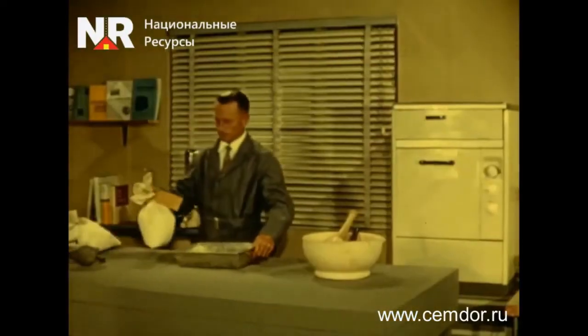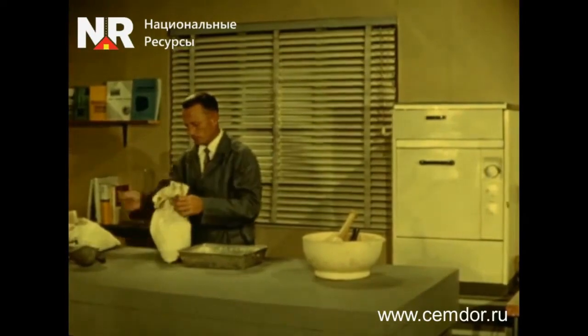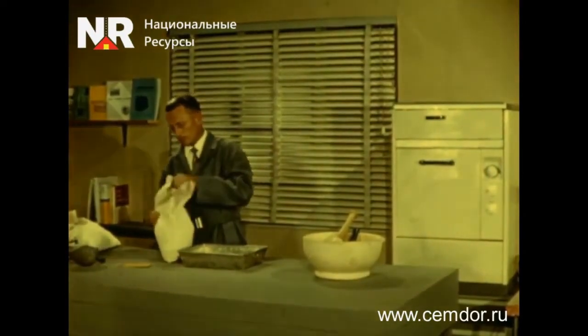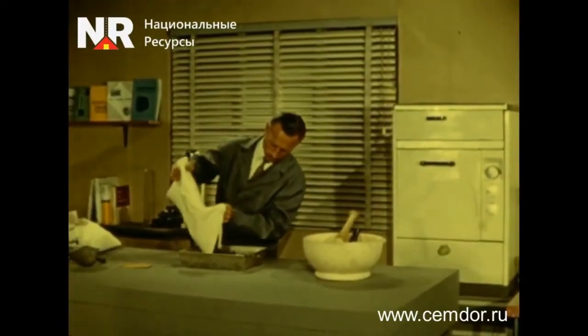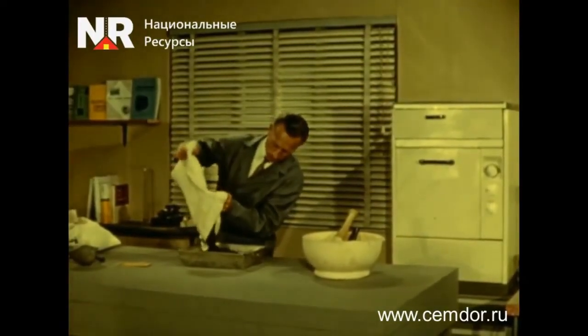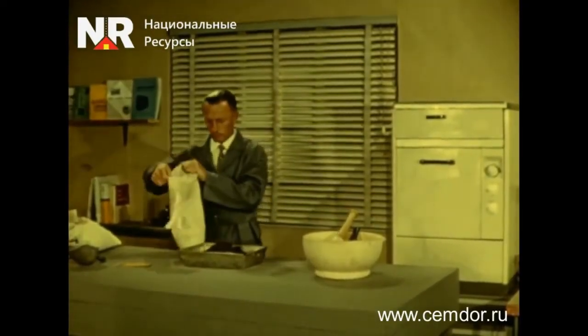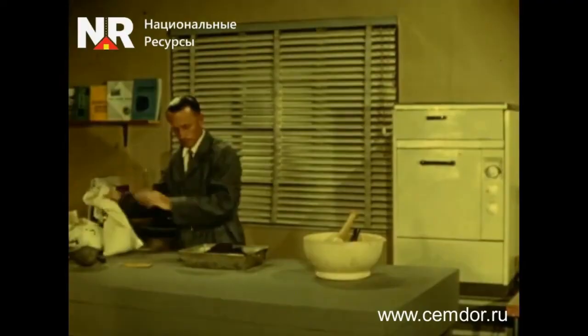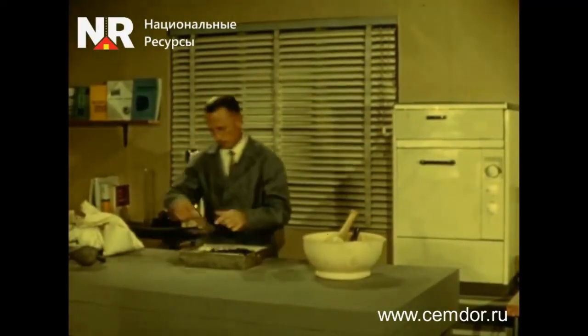In the laboratory, the samples undergo several tests to select the soil concrete mix, determining the optimal amount of cement and water to obtain soil concrete with the required set of physical and mechanical properties. When selecting the soil concrete mix, the first step is to determine the maximum soil density at its optimal moisture content using the standard compaction method.